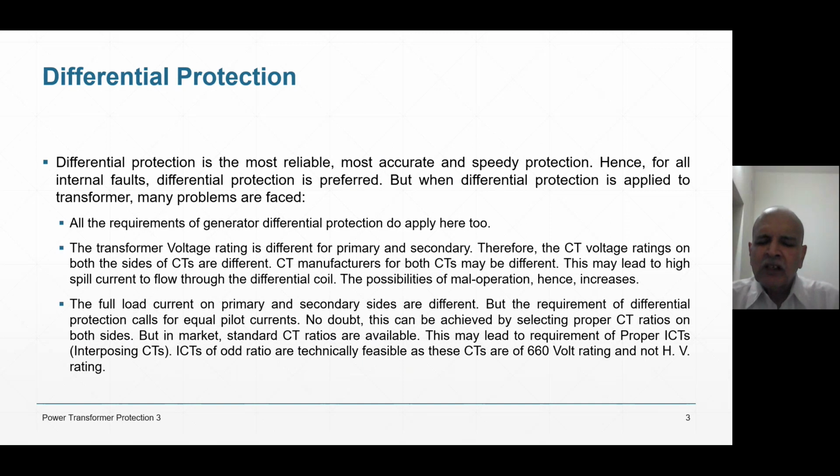No doubt, 3 sample technique is not that accurate. I mean, it may respond to noises and harmonics. Therefore, people use half cycle Fourier algorithm in which you will be able to sense the fault within half a cycle, that is 10 milliseconds.